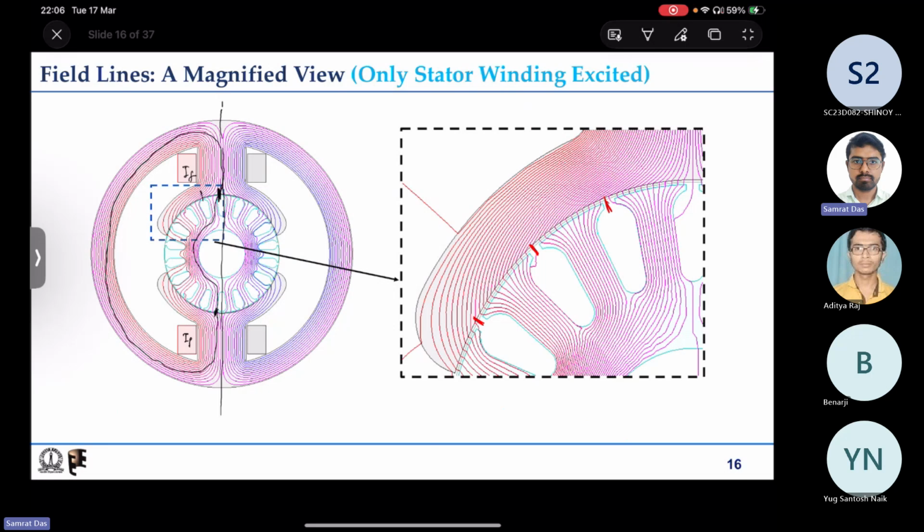Even if we take some other flux lines like this, any flux line from the upper 180 degree to the lower 180 degree, all the flux lines will have MMF distribution of basically IF, and minus IF on the lower side, plus and minus depending on the direction obviously.